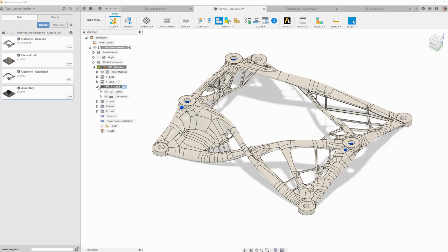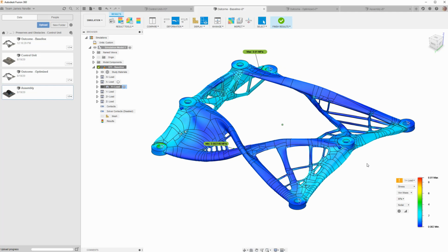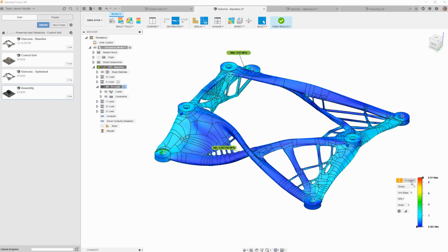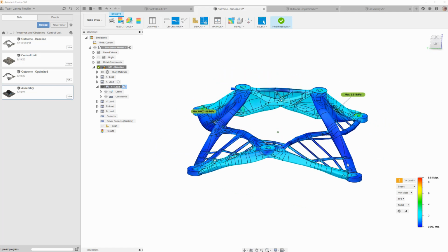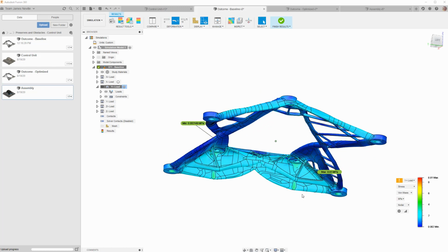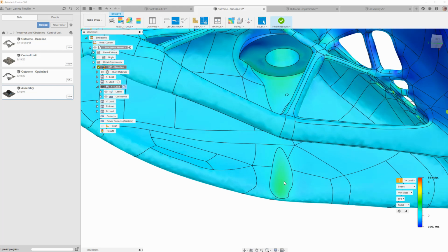Of course, all of your loads and constraints come through from generative design, which is super handy and time saving. Let's go right into some results here. So this is looking at some of the loads here. You can, again, go through all the load cases. But if you look at the Y loads, so that's the load from the left-right direction. Check it out. As we look at a stress plot, the areas where you get stress concentrations, this doesn't always happen, but right here, because of that gouging, this is now a stress concentration. This is significantly higher stress, like 2x more than the surrounding area because of that cut, right?